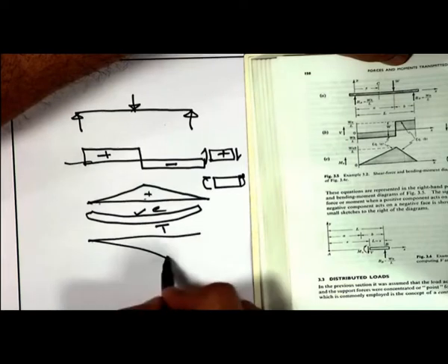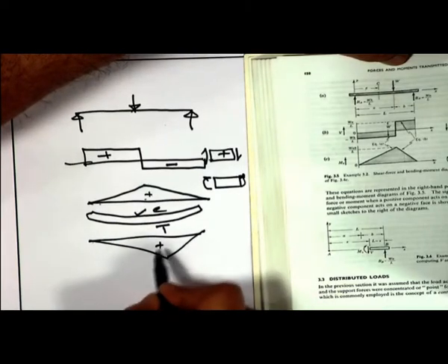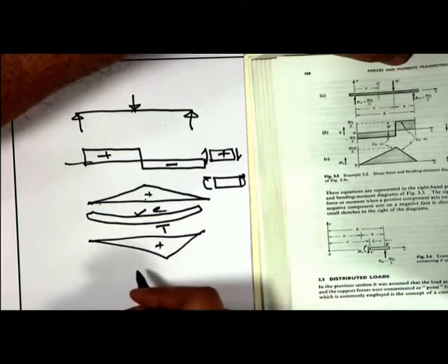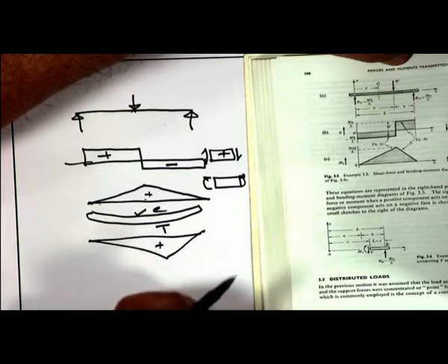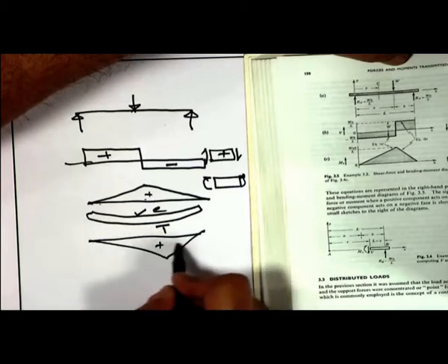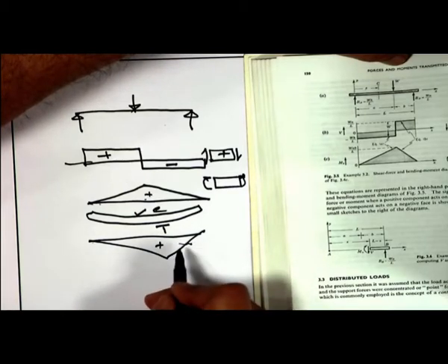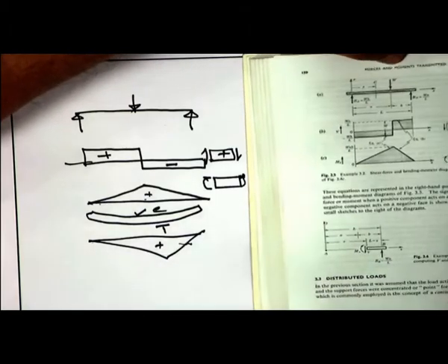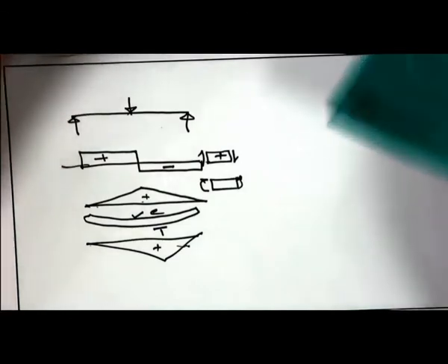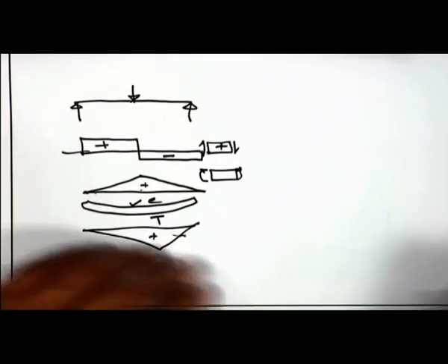Many civil engineers prefer to draw it on the tension side, because they can immediately find the locations of the reinforcements there. They need to stitch the impending cracked portion. That is why it is more appropriate for civil engineers to draw on the tension side. But again, it is completely arbitrary, and we follow it just arbitrarily.